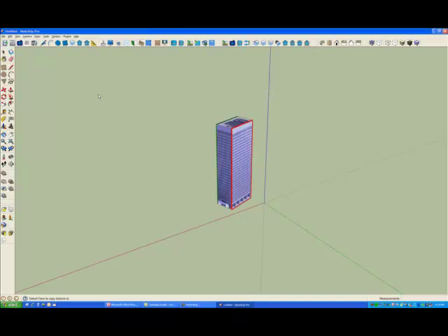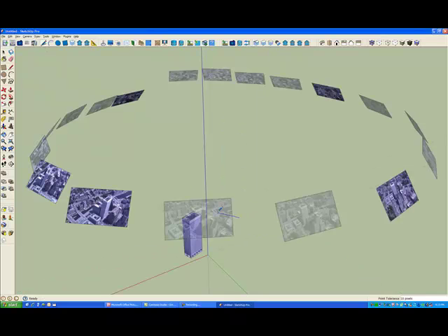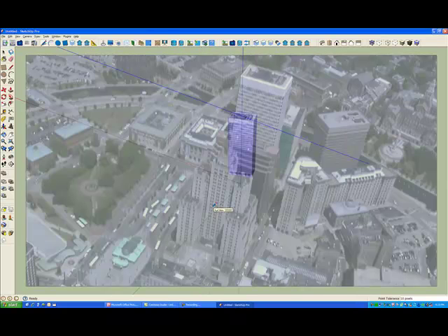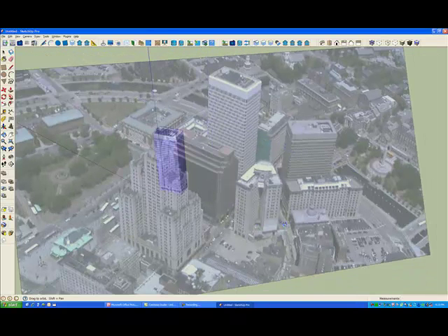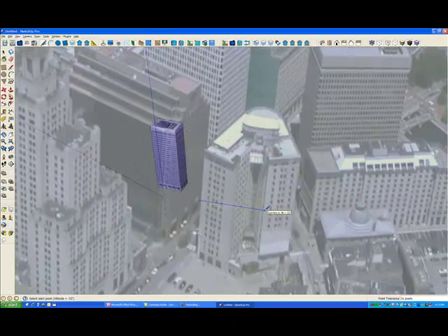Now I'll build a more complex case using the GeoSketch line tool. And we'll zoom out, and again we'll rotate around to where we can see the footprint of the building. But in this case it's a more complex profile. It would be easier to define it up at the top of the building than down at the street level. So we're currently still working at our altitude of -22 feet.